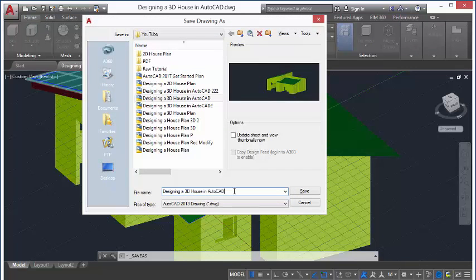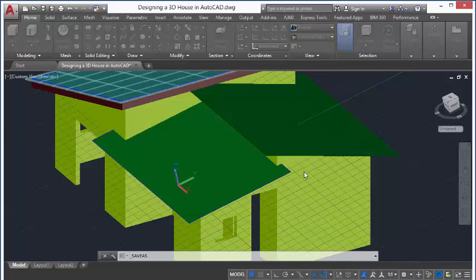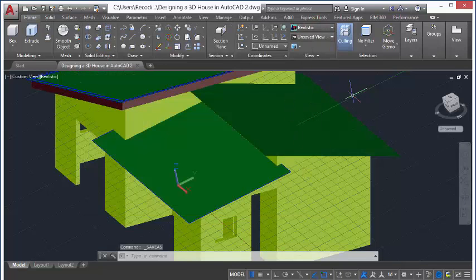As you can see, when you select the Save As command, if the drawing has been saved, you see the name of the drawing. So we want to make a copy of the original drawing. That way, if you want to redo the tutorial again, you still have your drawing intact. Press the space bar once and enter 2. Click Save to save the drawing where you saved the previous drawing.